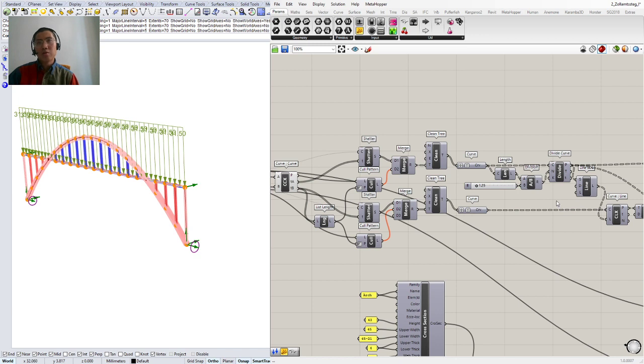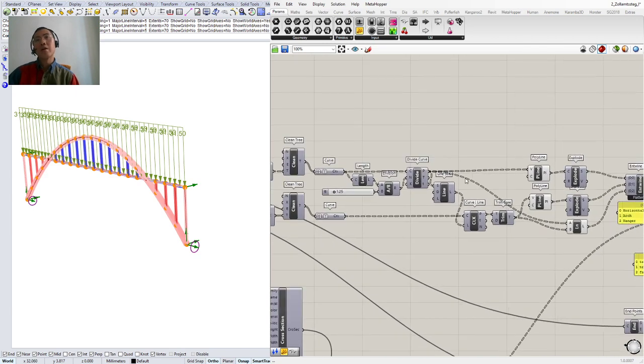You could try and uninstall Karamba and reinstall it as a free version of Karamba, and there you would have no limitation on the number of elements. There will be some components you see in the webinar that you will not be able to access with the free version. However, you will be able to still run the basic analysis and see the results on the truss with unlimited number of members in the free version.